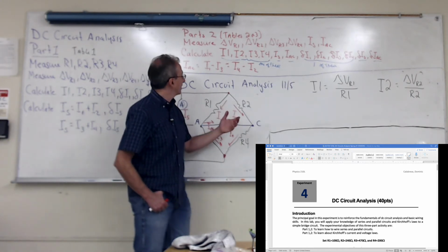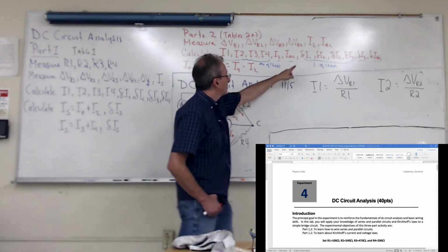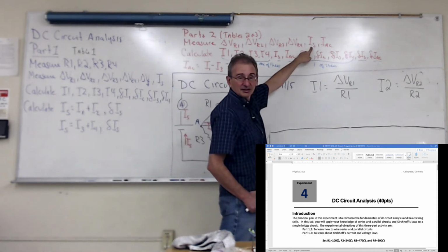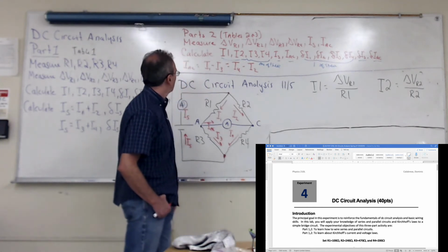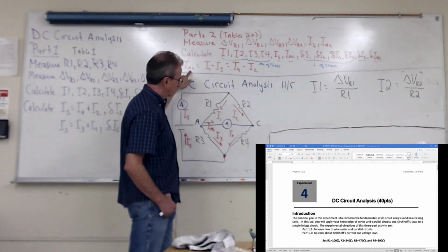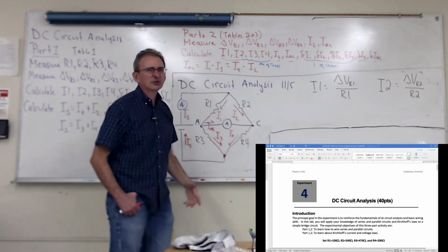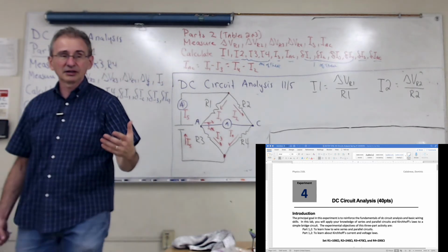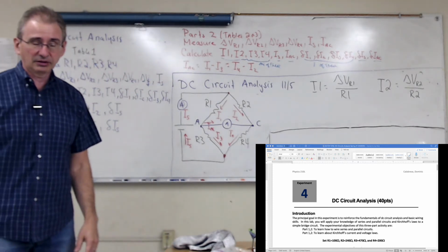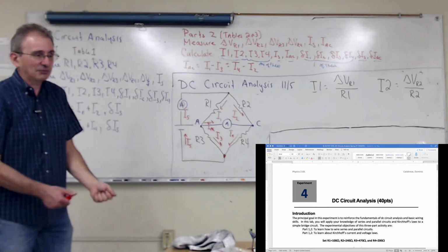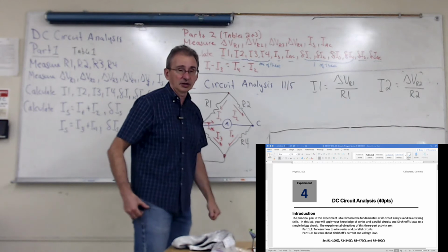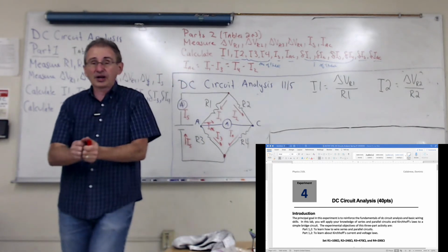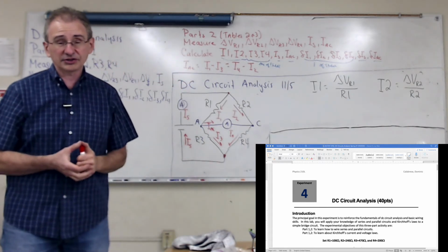And you're going to see this number change because of the resistance in the meter. That's what I'm trying to show you, the effect of the instrument on the circuit. So when you're making measurements, you also have to think about how your instrument affects whatever you're measuring, because that's important in science.